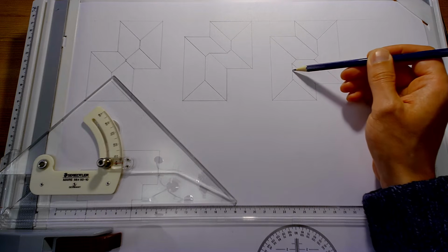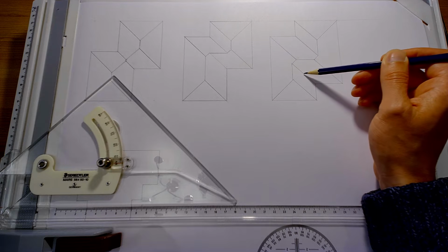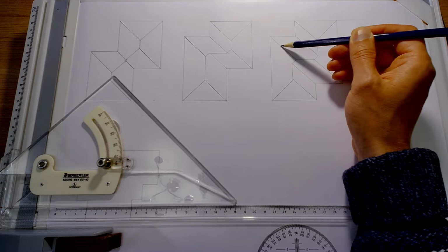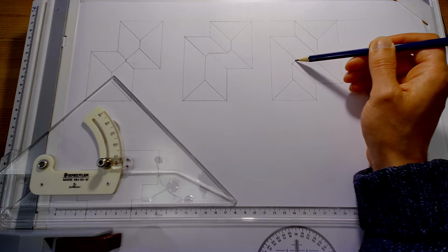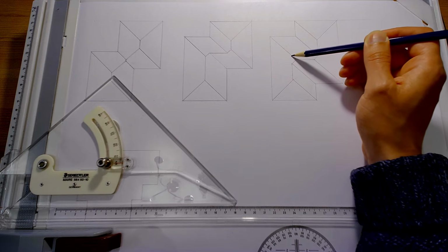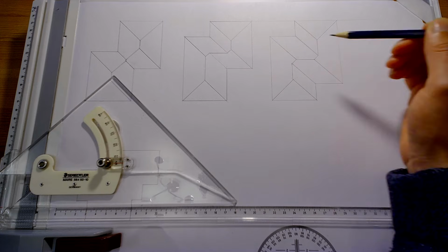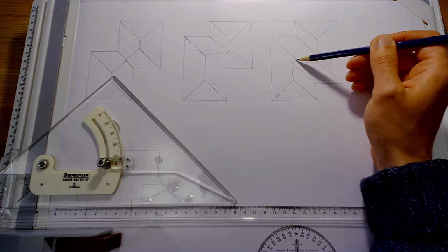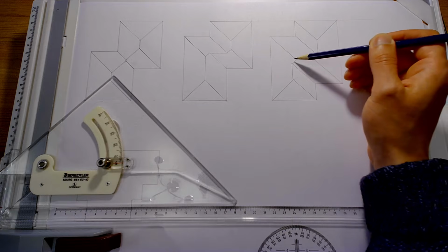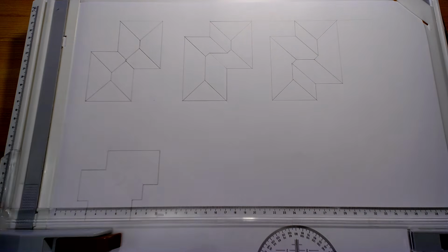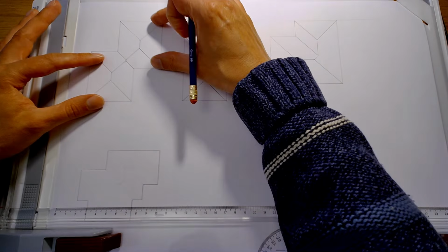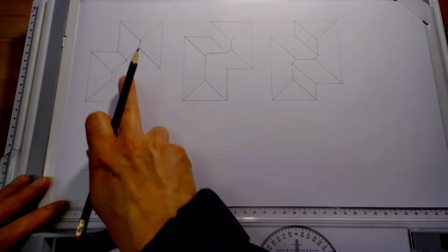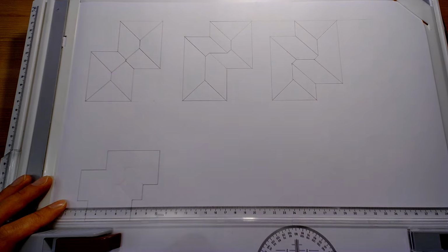So the ridge ran along and it hit the valley before it hit that hip over there. So we connected it by there, and then another 45-degree line comes off to join it up there. And same on both sides, and then that just connects up with a ridge going across there. So you can see that a very similar building, just with two rectangles, can create quite different roof shapes.